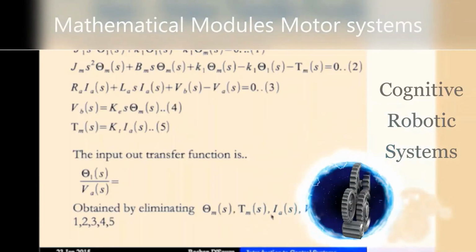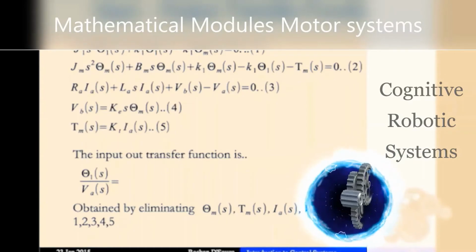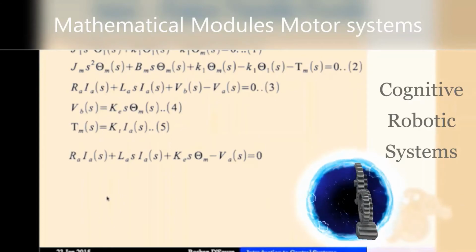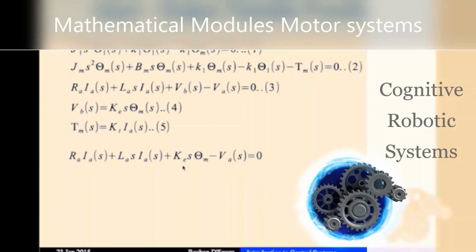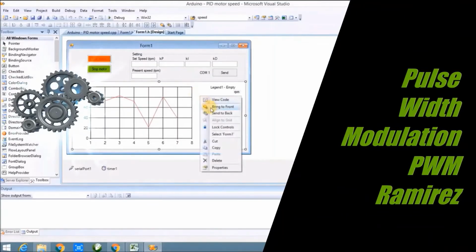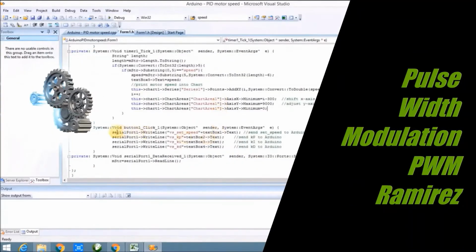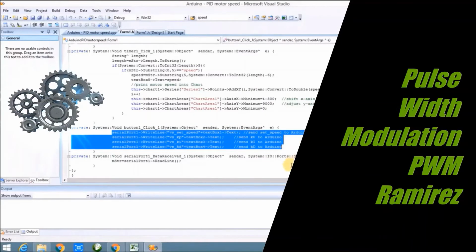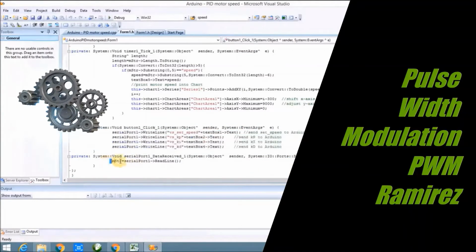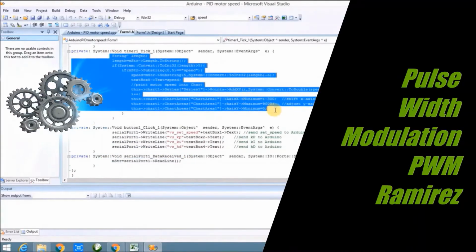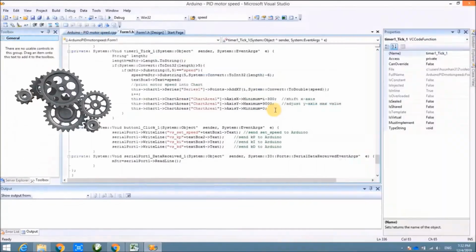It is done by cycling a digital signal off and on at a fast enough rate. With a certain duty cycle, the output will appear to behave like a constant voltage analog signal when providing power to the motor. In this application, the pulse width modulation duty cycle is used to vary the speed of the motor by controlling the motor terminal voltage.